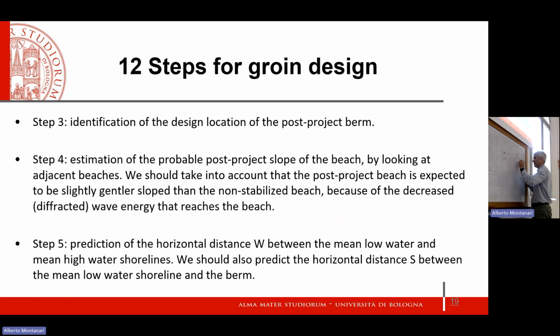This is the tidal excursion. So by knowing the tidal excursion and by knowing the post-project slope of the beach, let's call it phi, you can estimate W clearly with a simple trigonometric computation. This is quite obvious.